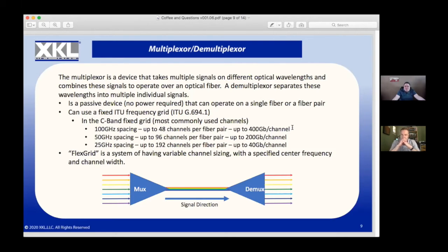When I say lowish, it's still not exactly free, but it has gone from 10 gigabits per channel to 400 gigabits per channel. Of course, they wanted to get more signals down the same fiber, because that fiber can cost literally hundreds of millions of dollars to put in place. So over time they reduced the spacing between those channels, so they can double the number of wavelength circuits you can put down a piece of fiber.